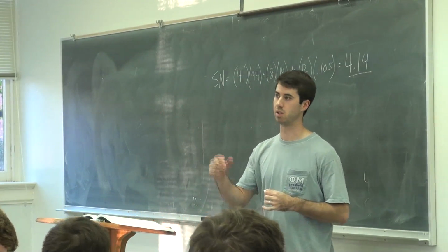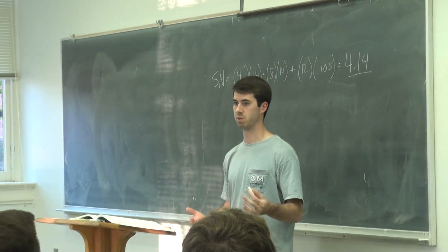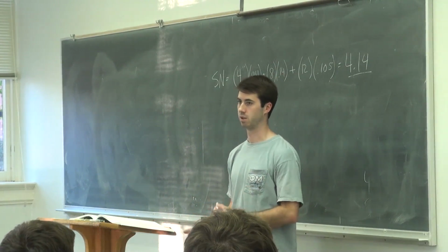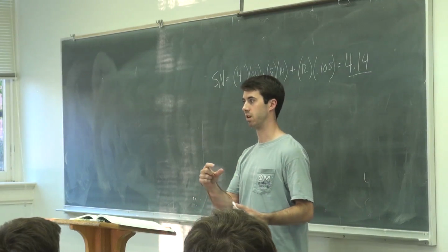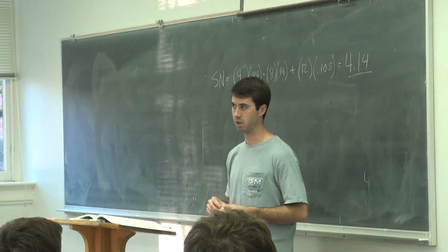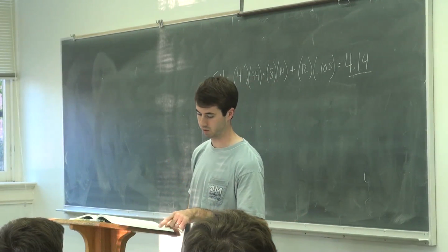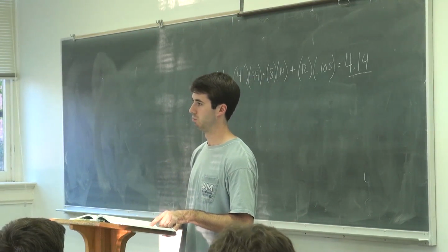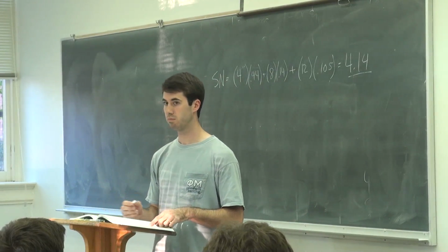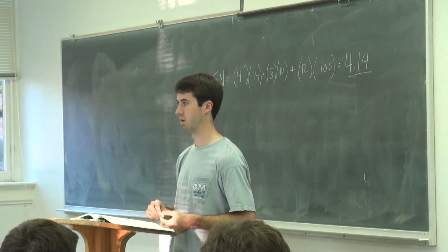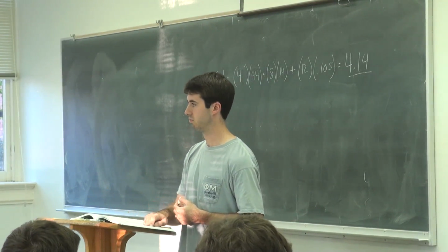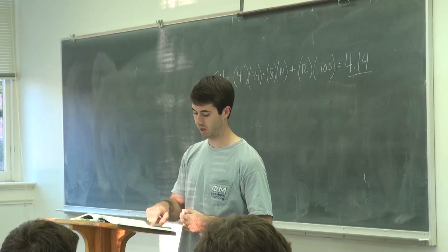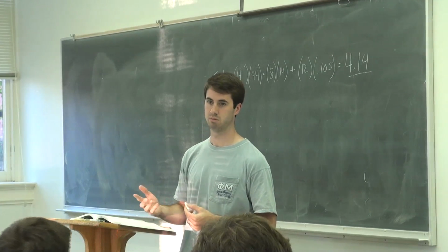And so things like this, if you can remember just what oven dry specific gravity means, that you're talking about a dry aggregate, so you've got a dry mass, you've got a volume with no water in it whatsoever. It basically means what this equation is right here. But then if you've got an SSD, now you've got to take into account the weight of the water and all that stuff. And so all you've got to do, if you know what you're looking at, is just add weight of water to weight of solids. Makes sense?